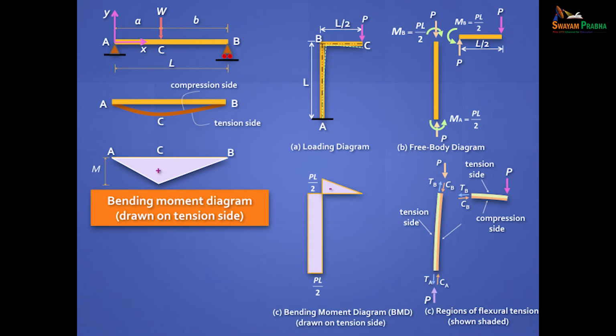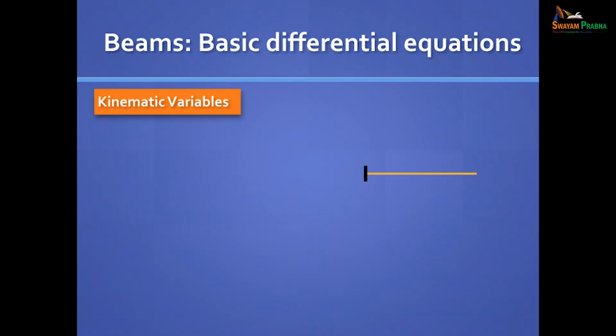So you get this feel only if you bring in kinematics. Now you see the deflected shape. This, you can say, must be part of a big circle. Why? Because you have pure bending here, pure bending with some axial compression. But not for this. In this, you have bending moment 0 here and maximum bending moment here. So the radius of curvature is going to change. Is it clear? Okay, we move on.